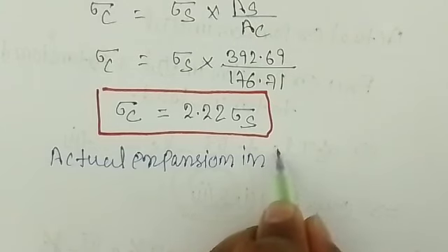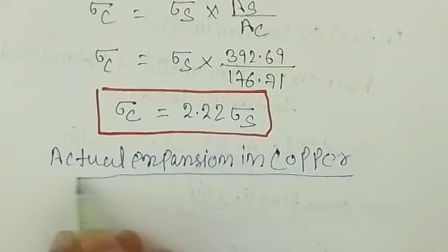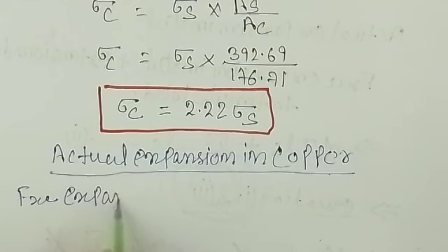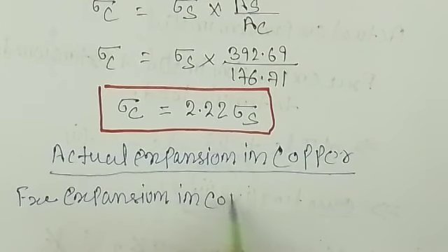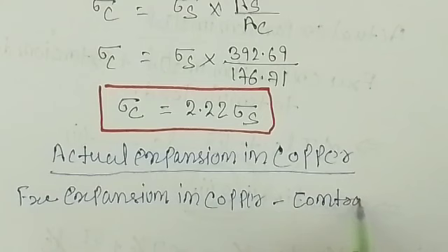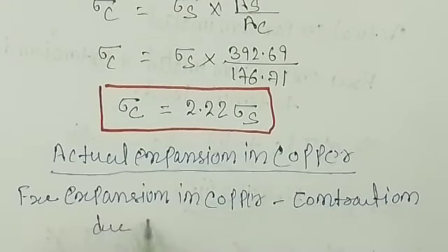In brass, in copper, right? In copper. So the actual expansion in copper is what? Free expansion in copper minus contraction due to compressive load, right?